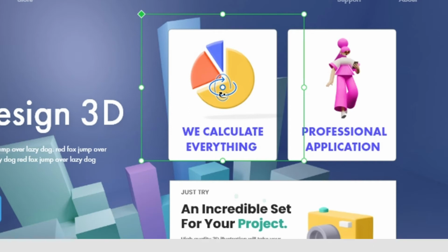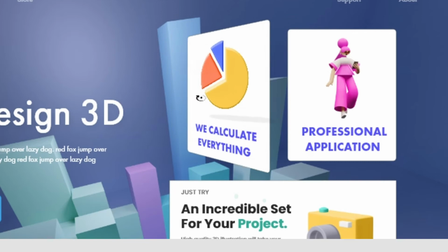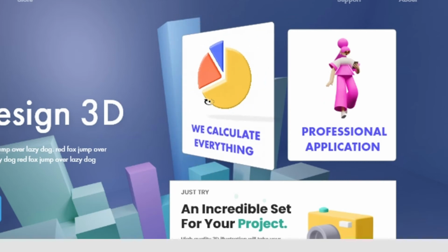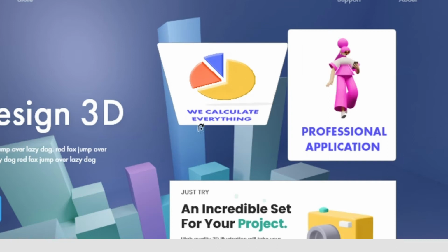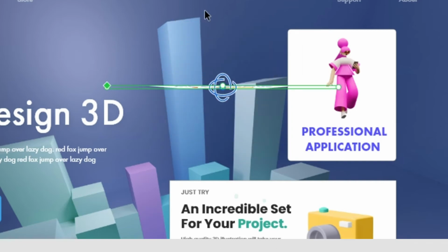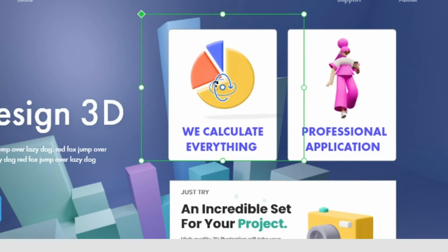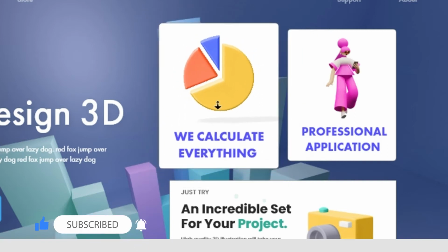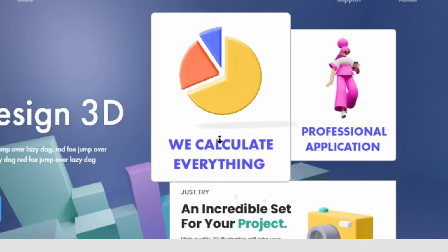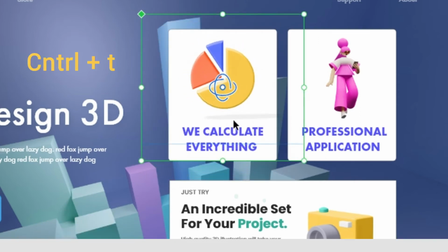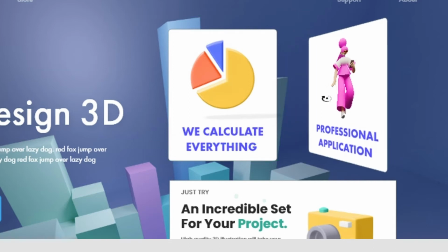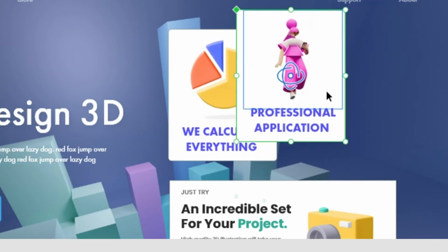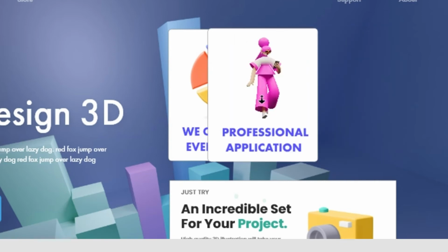What it does is it allows me to drag horizontally to change the y-axis of the card. If I select the second handle across here and drag up and down, it controls the x-axis, also from here to the center. Also, if you select the center dot here, by pressing and dragging, you can control the depth or the z-axis of the selected card, or you can say the group or the component. See how cool this is. You can simply rotate and feel it like it's in a 3D world, like we do in our 3D software.